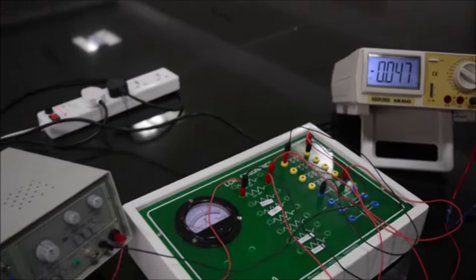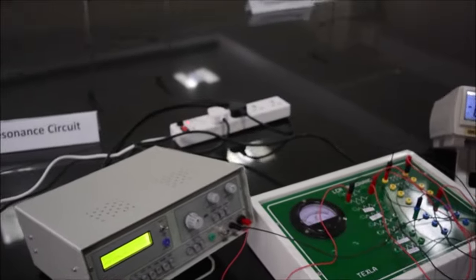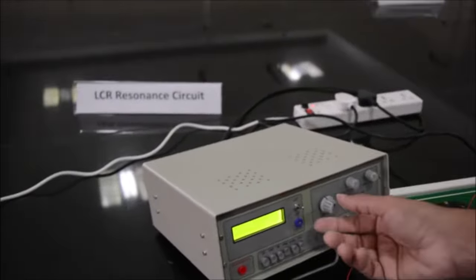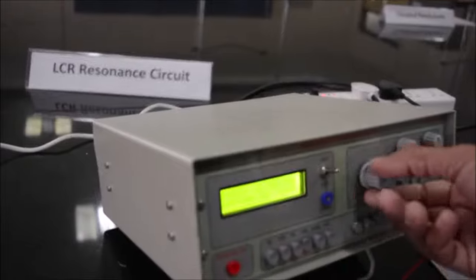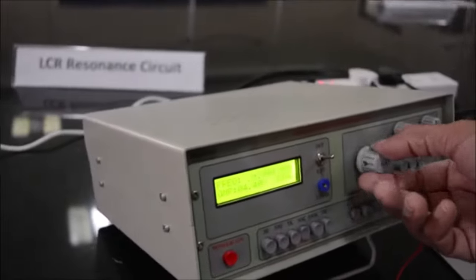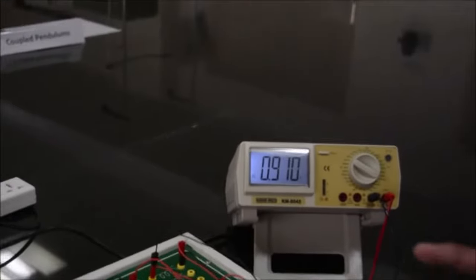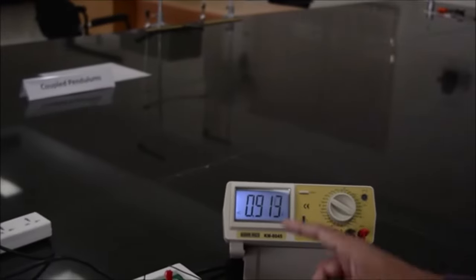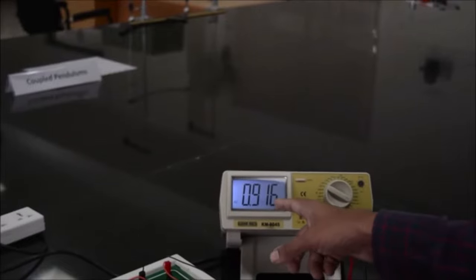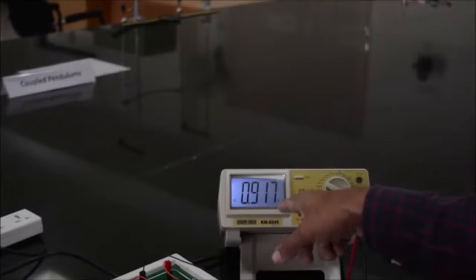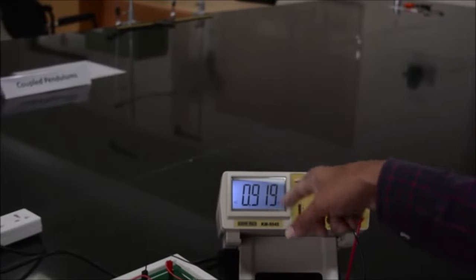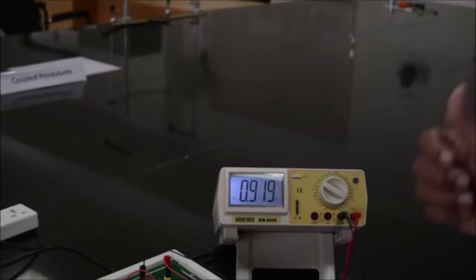Okay. Now we switch it on. Let's see what is the difference in the case of the parallel LCR circuit. Now again, let's start with a very low frequency and then observe what happens when I do a sweep of the frequency. So I'm starting with again a low frequency, but now you observe that the behavior is very different. Earlier for a very low frequency we got a very low value for the voltage, but now you observe that the value of the voltage is much higher, which means the power dissipated in the circuit is also higher.